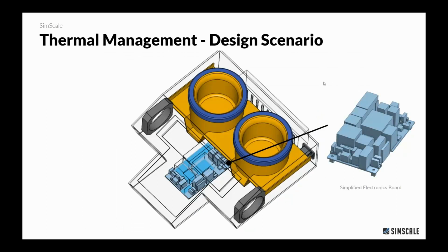Here, just quickly, to not make this a canned demo, what was done, you've seen it already, is that from the original design that had all geometric detail on the electronics board, we used a specific feature script inside Onshape that allowed us to automatically remove the detail of that electronics board, which comes in quite nicely and is helpful for the CFD part of that.